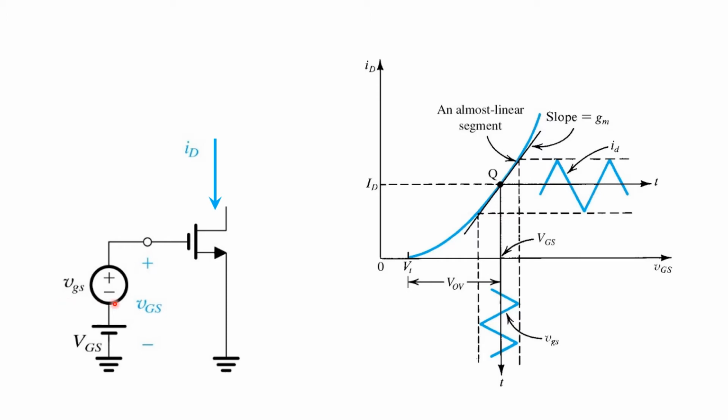As long as the gate source voltage exceeds the threshold voltage, this is going to give rise to a drain current, shown here ID. Although we haven't explicitly shown what the drain is connected to, let's assume it's connected to some circuit so that VDS is definitely greater than the overdrive voltage applied to the MOSFET for any voltage excursions that we see at VGS. So whatever circuit is connected up there, this condition is maintained, and as a result, we know that as long as the transistor is on, it will be in saturation.